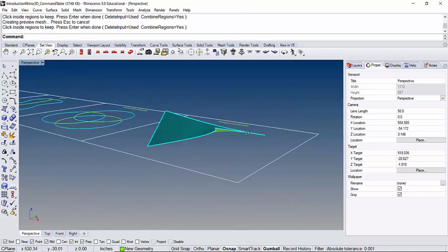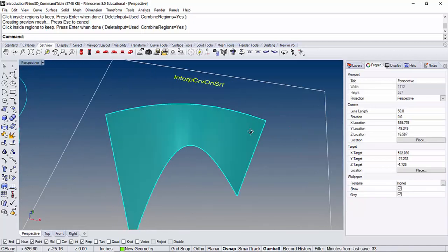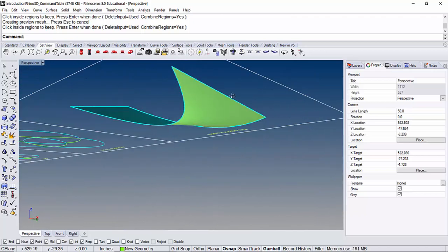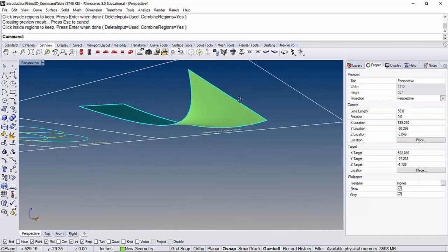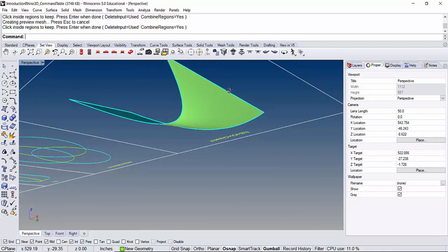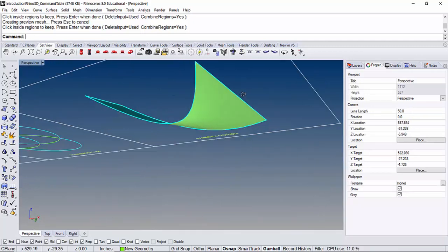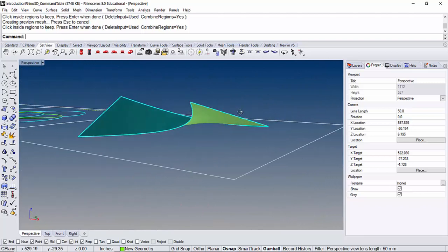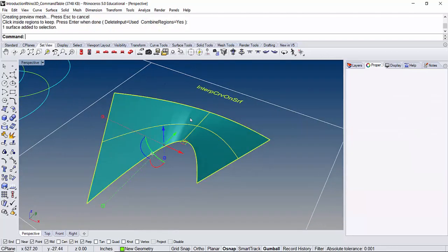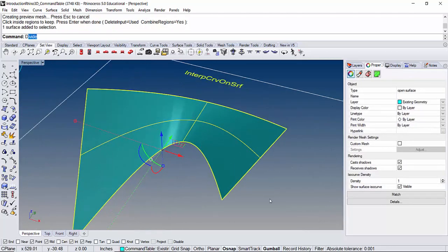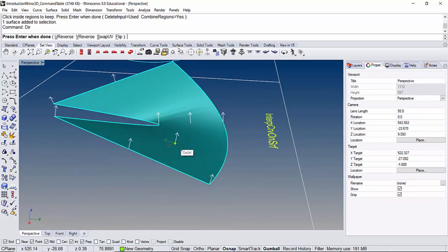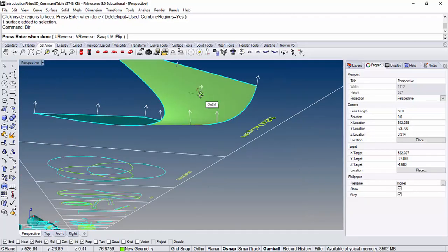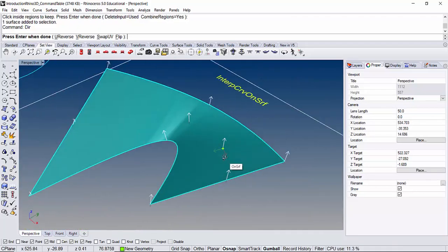All right. This next command is one of my other favorite ones. Now, does everybody see the back of their surfaces with a different color? Yes? So remember, this is a function that we set up yesterday. If you select your surface and type the command dir, wherever your arrows are going towards, that's the front of your surface. The back side is a different color.